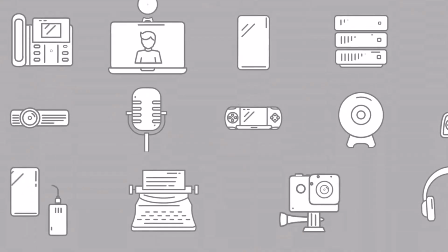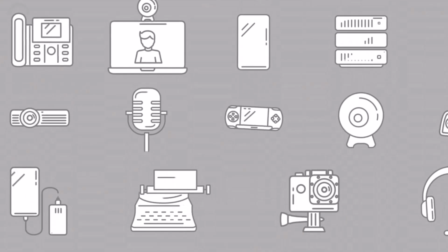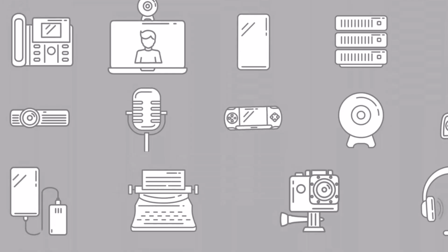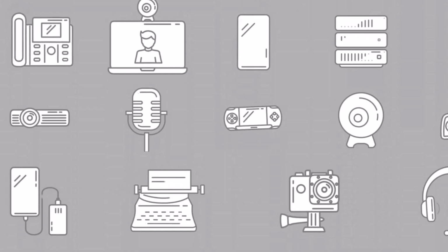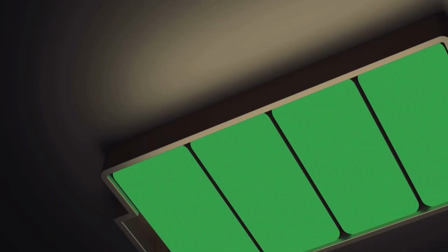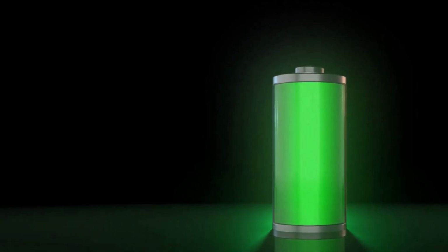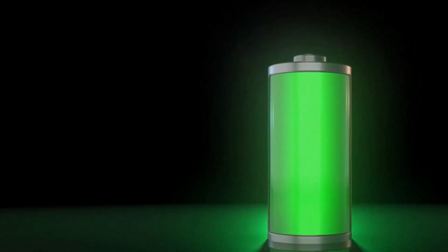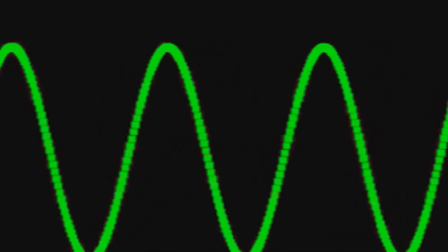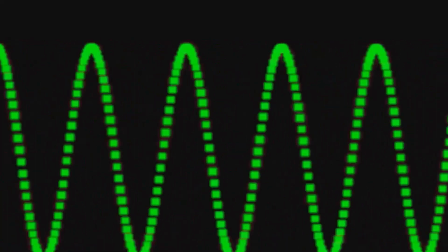Because of this inefficiency and the pulsating nature of the output, half-wave rectifiers aren't used for powering complex devices like computers or smartphones. However, they do have their place in some very simple, low-power applications where a rough DC signal is acceptable. For example, they might be used in simple battery chargers or basic power supplies for projects that don't require a steady flow of energy. It's a good starting point, but for most of our modern needs, we need a way to capture all the energy the AC wave has to offer.